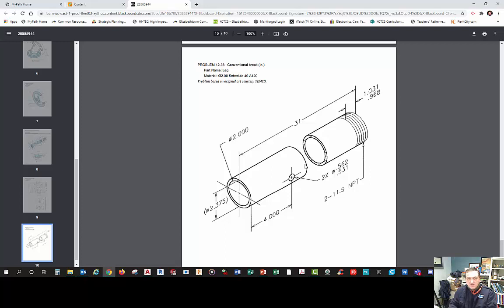You just need to draw the end of it and the end of it, and if there's a feature over here, you draw that much, but then you can leave out a bunch of it and just shorten it up so it doesn't take up a big chunk of a piece of paper just for this long object that's the same. So what we can do is we can cut it out, and then we can do a broken dimension.